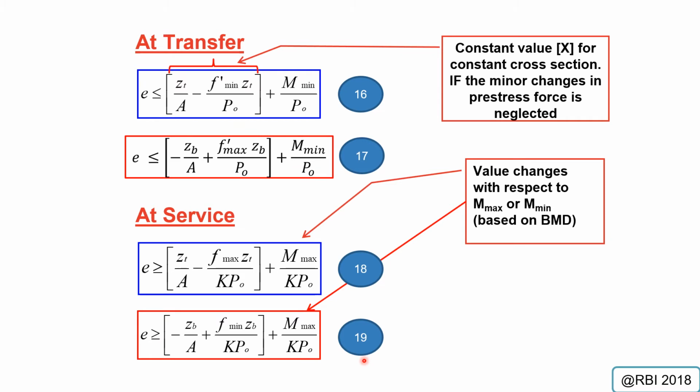Okay, one thing that you might want to take note of is the values of your moment. The values of the moment will change depending on the location of E that you want to find. For example, throughout the length of your beam, if the position is at the end of the span, your moment might be equal to 0.